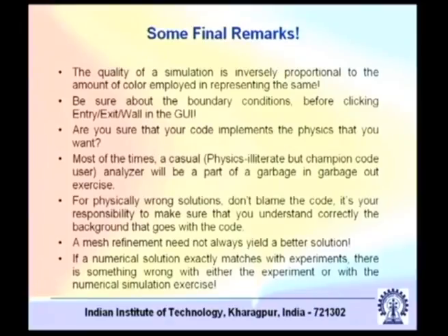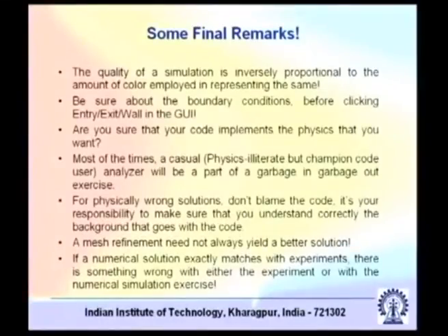So you must make sure that your code implements the physics that you want. That is very important. If you are unsure about that, first make sure what the governing equations are, and whether it is possible to cast those governing equations in a conservative form. If it is not possible, then this CFD code is not for that particular problem. Everything is not for everything. It is not that you have a CFD code which you can use for solving any problem. A CFD code fundamentally is a PDE solver. So it is a coupled PDE solver, so to say.